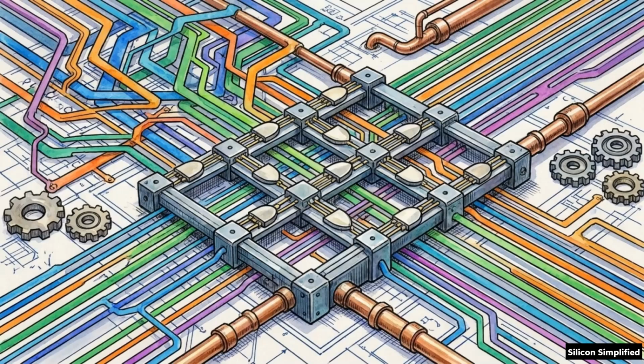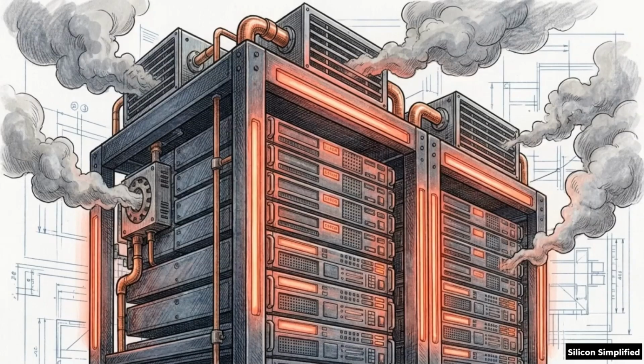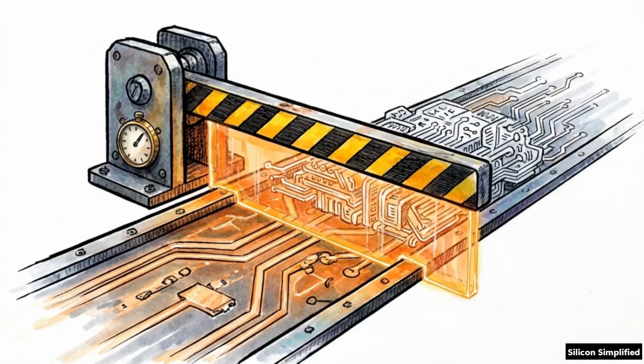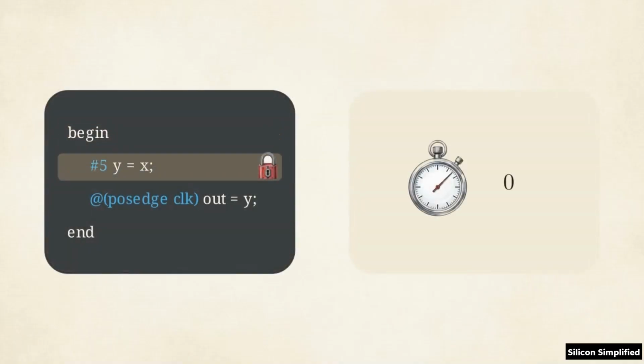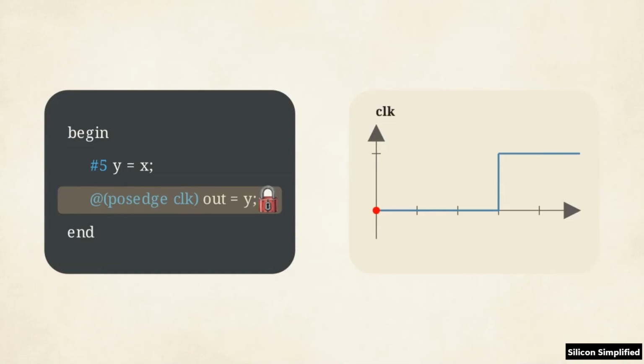Designers must use specific tools to force strict order onto the system. An infinitely looping always block will completely lock up the simulator. We need internal routing mechanisms to regulate exactly when these independent blocks evaluate. Timing controls act as execution barriers, suspending a block's activity until a required condition is met. The most basic is delay control, represented by a hashtag. Writing #5 suspends execution for exactly 5 simulation time units before allowing the process to continue.